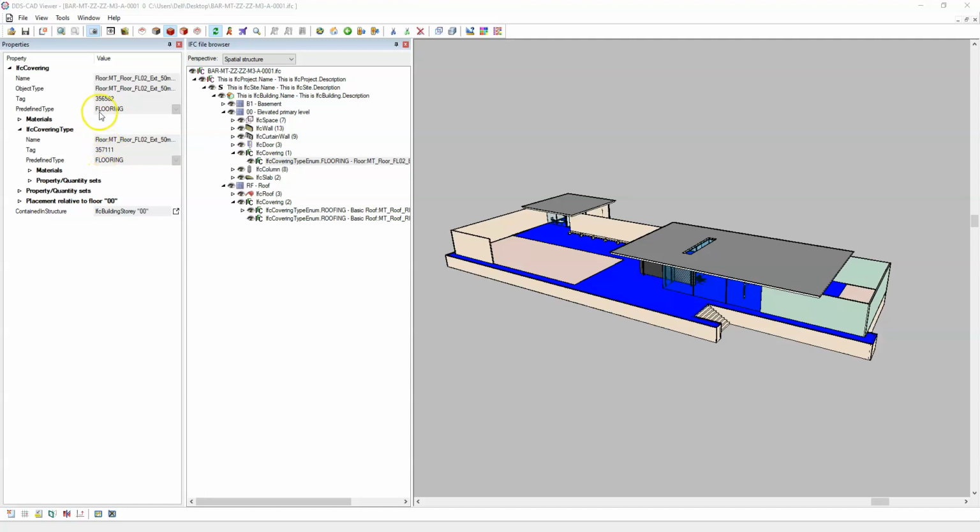However, the attributes visible here are not very useful when it comes to relating the information to documentation, schedules, or specifications. Therefore, we need to update this information and add additional attributes as required to ensure that the attribute information in the IFC aligns to that produced within the design and construction documentation.